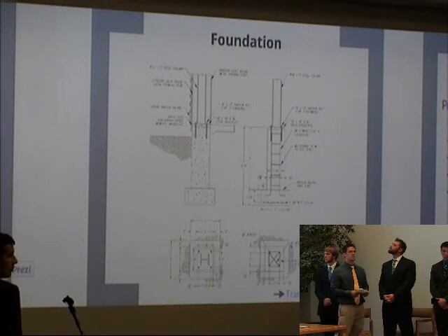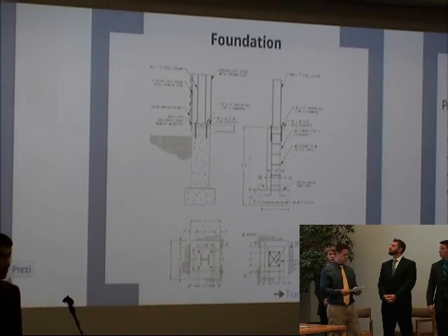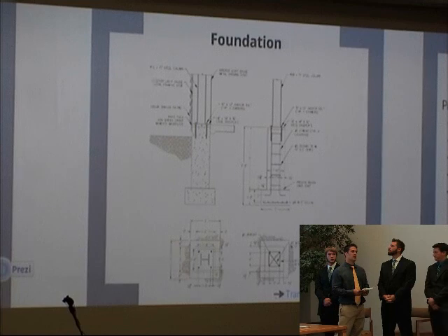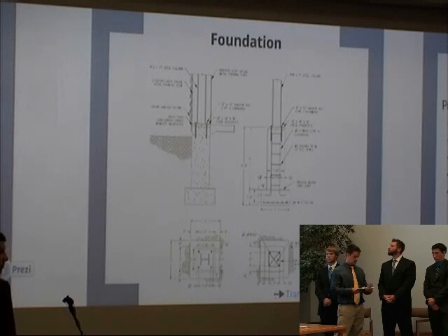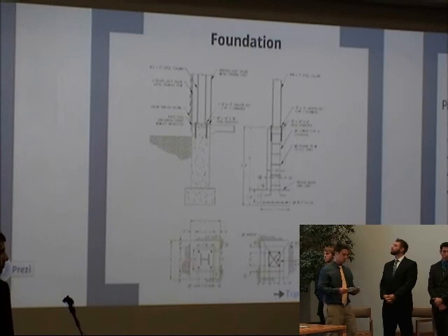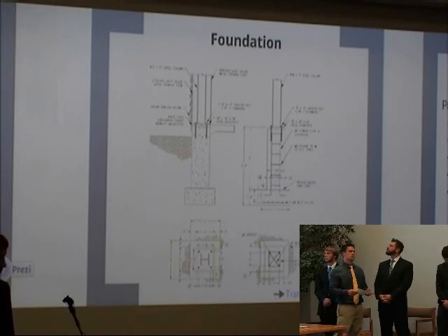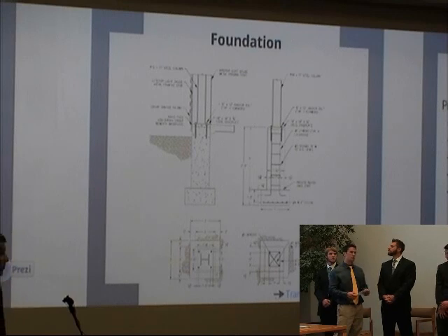Shallow foundations transmit structural loads to the soil underlying the ground surface. Then there are 2 different types of shallow foundations, spread footings and mat footings. Mat footings are necessary with poor soil conditions and high structural loads. We had neither. The loads of the structures were similar and relatively small. Therefore, spread footings were chosen.